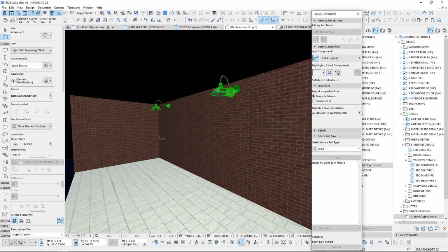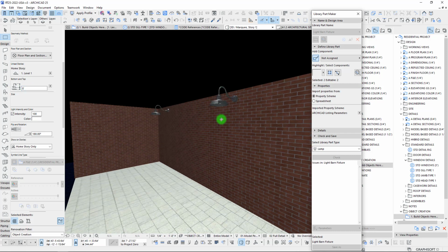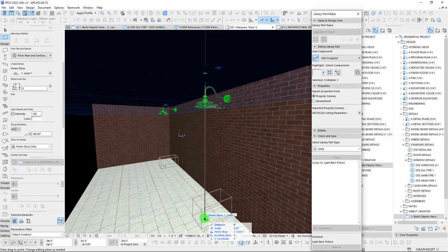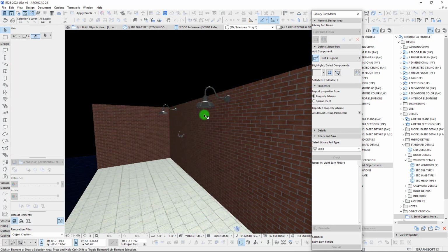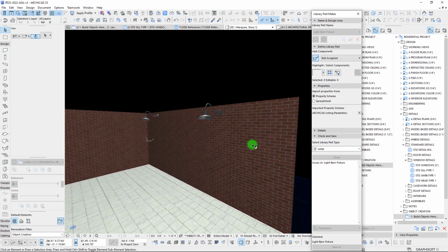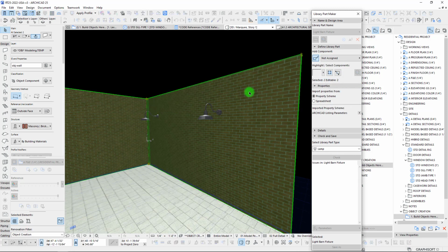With our new base insertion point, we can see that we're at 8 feet here. That's where we want it. If we drag this down, that's a distance of 8 feet. So perfect. That way, when we specify the bottom of the light fixture, it's exactly where we want based on our elevation settings. Sorry, that's something I should have pointed out earlier.